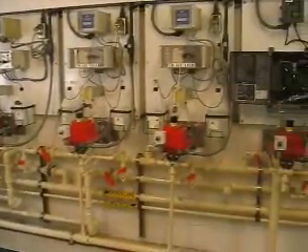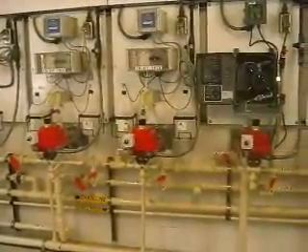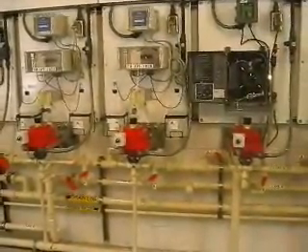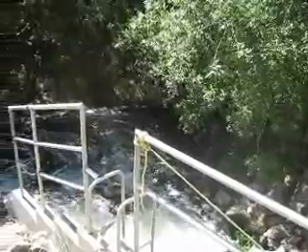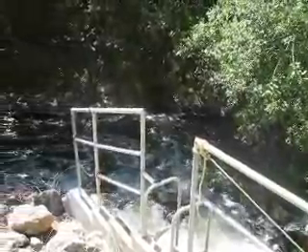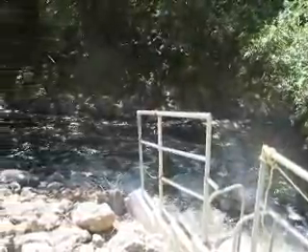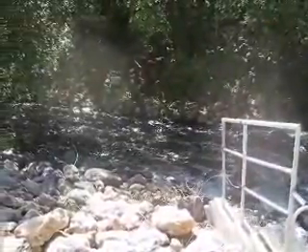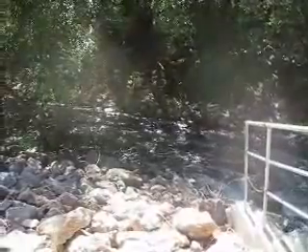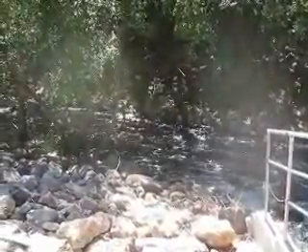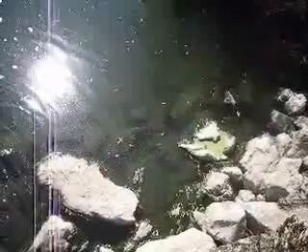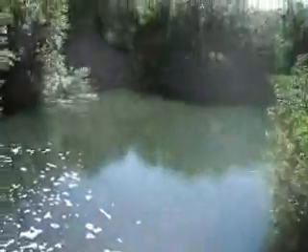Turbidity, chlorine, and sodium bisulfite are tested, as well as other wastewater constituents. The crystal clear water is then released into the North Fork of Arroyo Conejo Creek. Some of the reclaimed water is diverted for agricultural reuse on farmlands in the Santa Rosa Valley and the Oxnard Plain. Using reclaimed water reduces groundwater pumping and overdraft problems, and also helps prevent seawater intrusion in the Oxnard Plain.